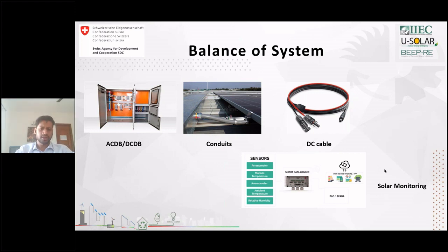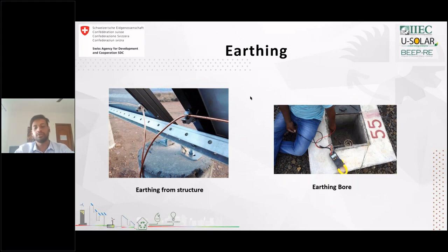With cloud-based systems and some estimation tools, we'll be able to determine whether your solar plant was generating ideally for the amount of irradiation available. If there is a deviation and your plant is generating considerably less than what is expected, then we can identify that there is some sort of issue and it has to be rectified. That's the main purpose of your monitoring system.